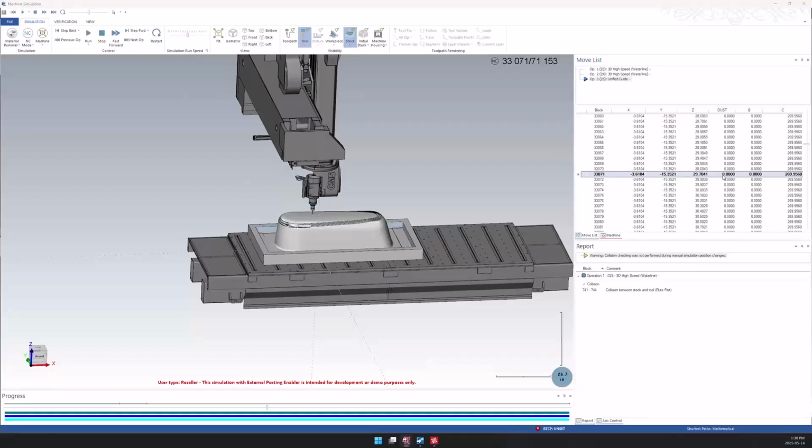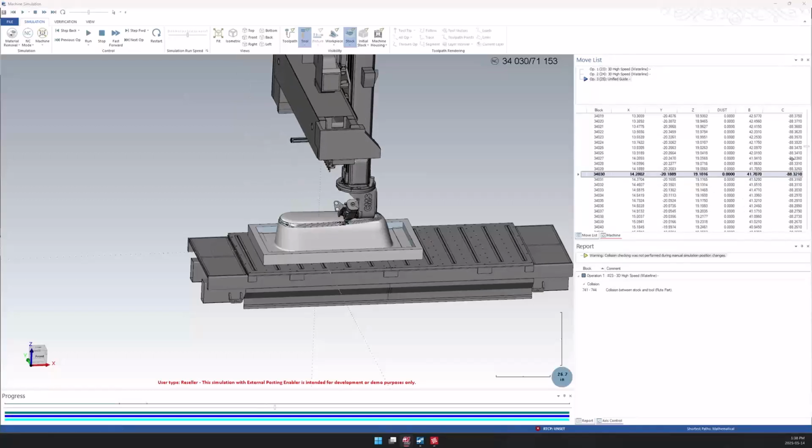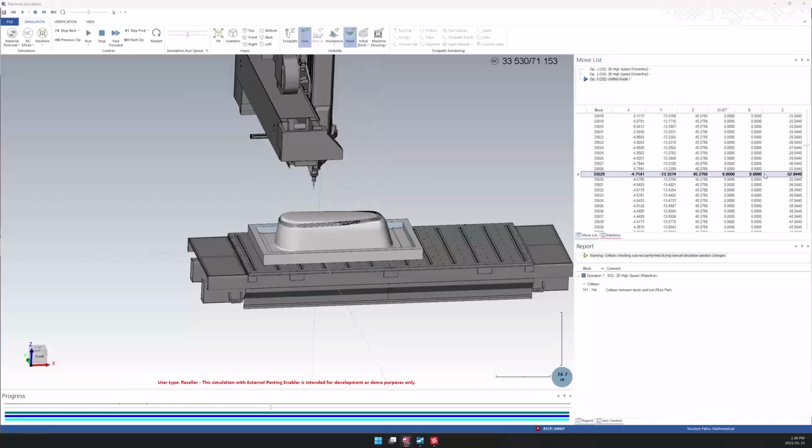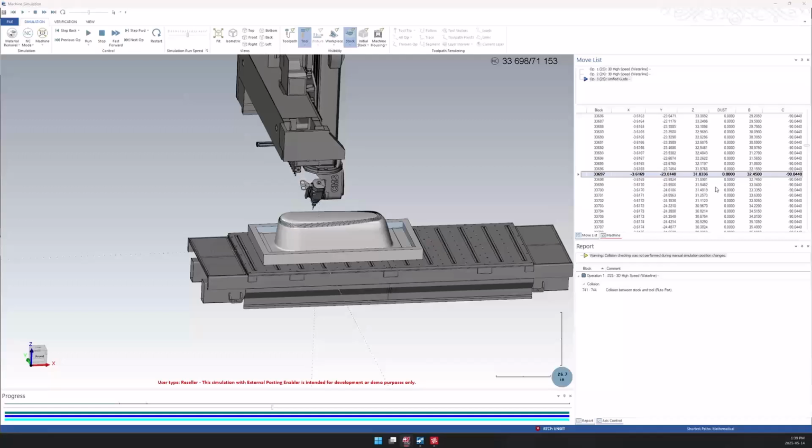So I'm retracting. So now I'm going backward. Sorry. I'm at the end of the rotation, so my tool retracts. Oh, my bad, trying to go too fast here. Skipping the actual motion, it basically unwinds the C-axis and then re-engages, and that's the actual motion that you should see on the machine right there, because this is the retract motion that we generated from the post.